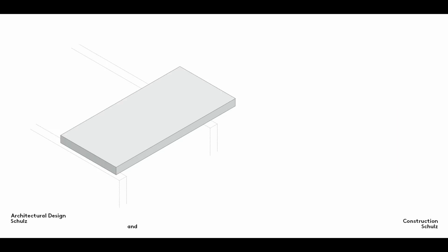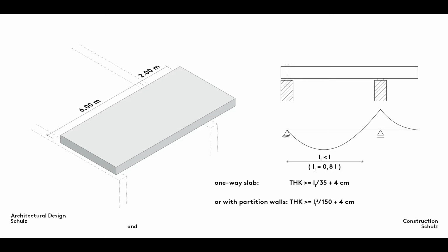When designing and dimensioning a solid reinforced concrete slab, it is important to analyze the various factors that will affect it. This means determining the types of load that may occur, calculating the loads to be transferred, designing the load-bearing points, linear or single point, and deciding the span width and direction of the floor. Once these points have been clarified, it's time to calculate the slab dimensions.